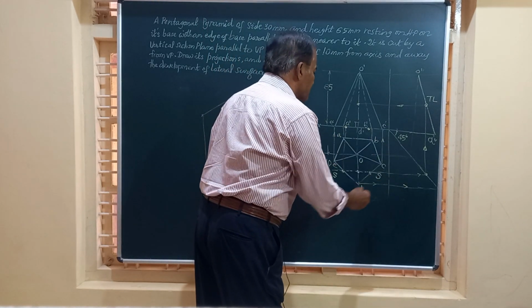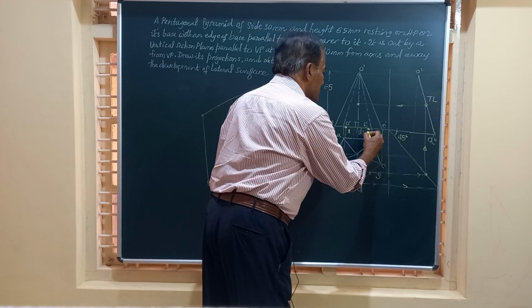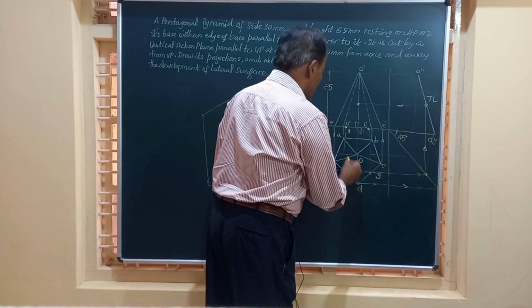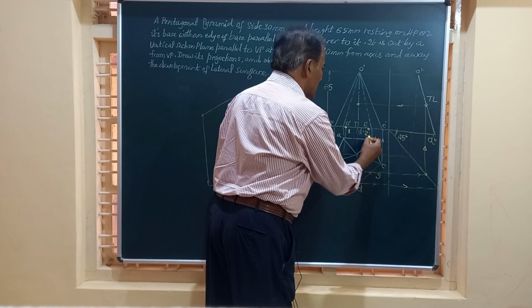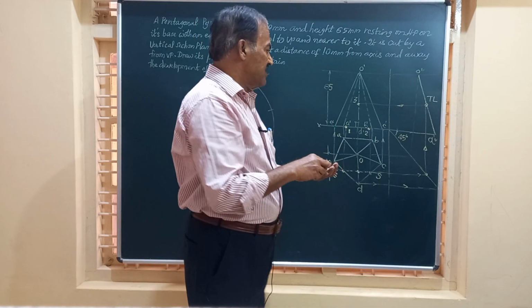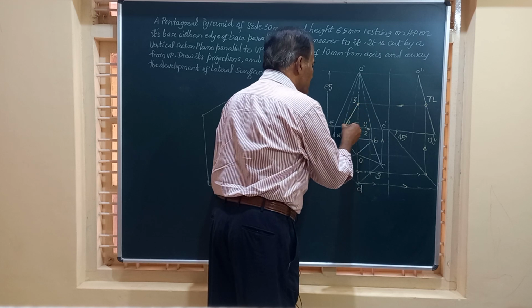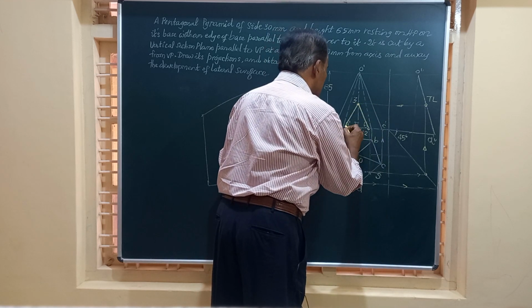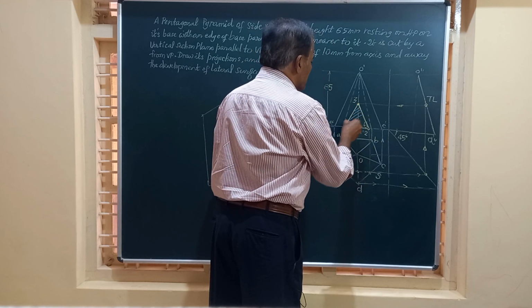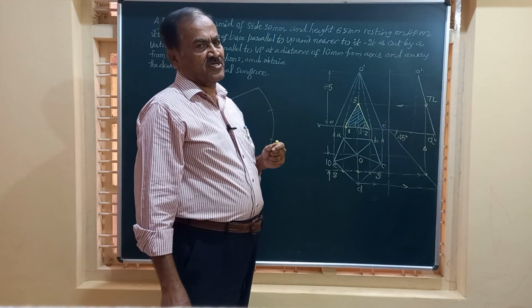Friends, these are the 3 points, and we will show these 3 points as 1, 2, 3. This is 1, this is 2, 2 on this, 1 on this, and this point is 3. For all the pyramids, these are to be joined by the so-called straight line. So I am going to join this like this, second from here, third here, and friends, I am going to section it or hatch it by lines drawn at 45 degrees to the horizontal. This is how this section looks.